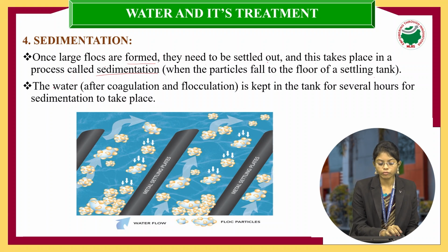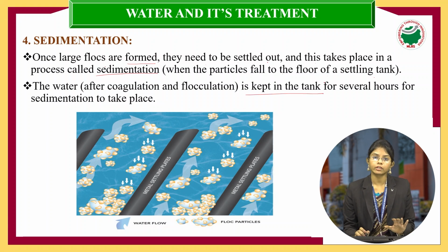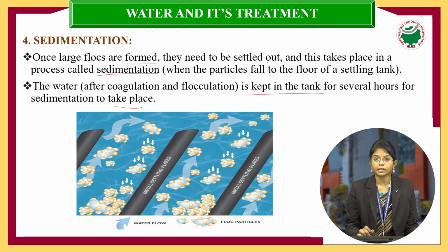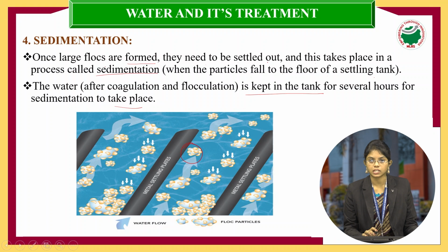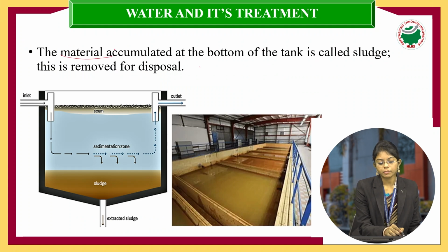That means now the water is kept in the tank for several hours. So after forming the larger flocks, you leave the water for several hours so that all the larger flocks will settle down and sedimentation takes place. So you can see all these larger flocks can be settled down if you keep your water aside for a few hours. The material is accumulated. What is the material here? The large flocks.